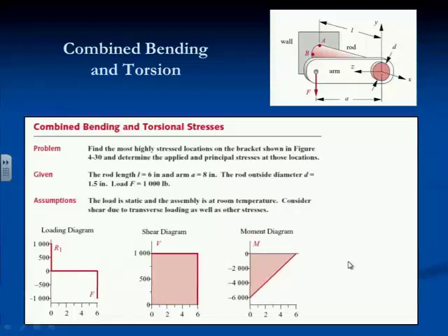So the moment diagram is the integration of that. So again, I could walk across the beam. Now I'm walking across this diagram. I'm recording the area that I see, which of course is the integral, right? And by baby steps, I see a little bit more area. So I'm going to get this. Actually, I have to walk the other way, come to think of it. I got smart. I decided I'm not going to fall off the beam the second time. I'm going to walk this way this time, so I walk toward the wall. The difference has to do with the sign conventions, which are silly because the shear convention's opposite to the moment.